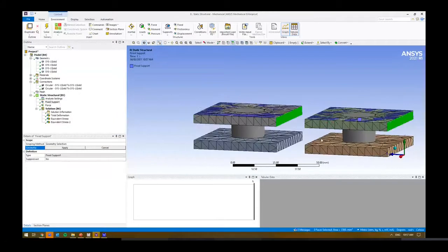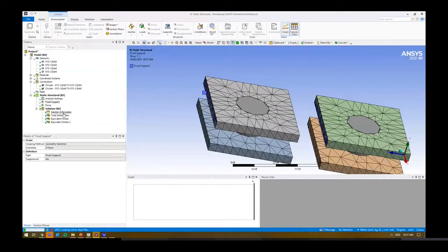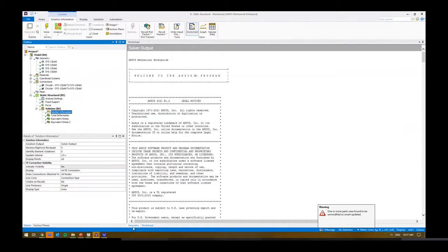So what we might do, we might go in and just make some changes to the boundary condition. Run that again quickly, just to make sure we've got some constraints that make sense. I guess that's another thing as well. When you're doing these constraints, you just want to make sure you really think about how you're constraining the nodes and elements around here. If we've got overlapping constraints, it can sometimes become a problem.